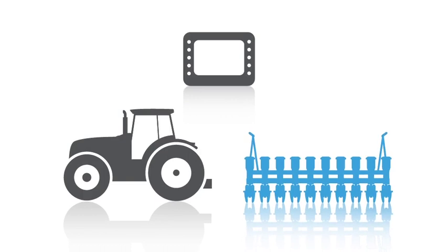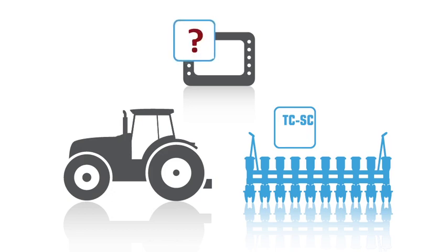Each functionality can be explained as an independent module on the Isobus. In this way, a functionality is also a product you can sell. However, one of the most important things about compatibility is that the lowest common denominator rule applies for the number of functionalities that can actually be used with a tractor-implement combination. This means only if a certain functionality is supported by all components involved, i.e. tractor, terminal, implement, the operator will be able to use it.